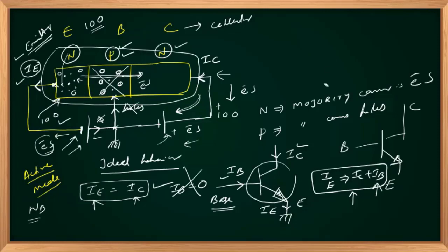And the bipolar junction transistor falls under the category of a voltage controlled current source. Please don't confuse, it's not a current controlled current source. It's a voltage controlled current source because there should be a voltage to turn on the respective regions, and the output can be modeled by a collector current IC that is proportional to the number of electrons emitted from the emitter side. That in turn depends on the magnitude of the base emitter supply voltage. So it's a voltage controlled current source.